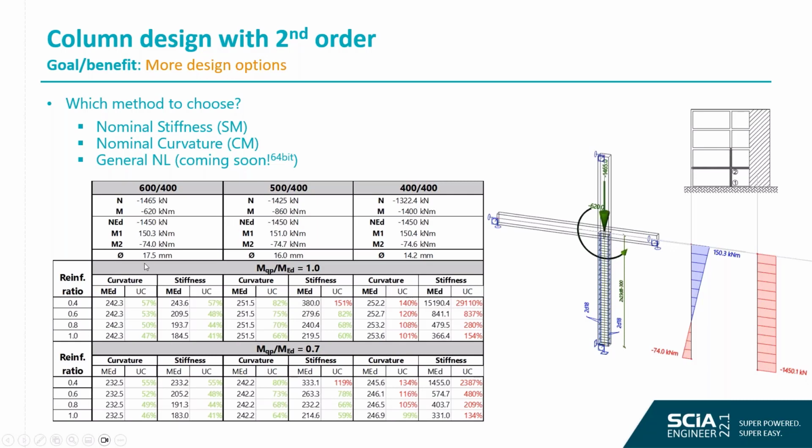Here you can see that the numerical study will focus on changing of the cross section and also changing of the reinforcement ratio. And yeah, because this model is undetermined, it means that always the applied load is a little bit different, but the internal forces, first order moments and axial load will be for all options the same.